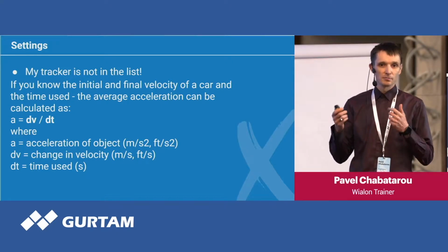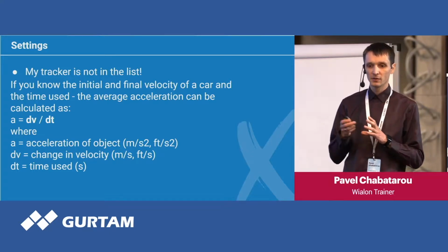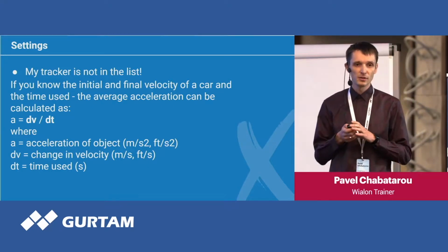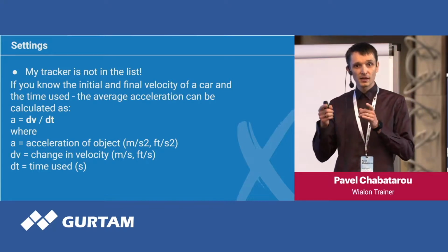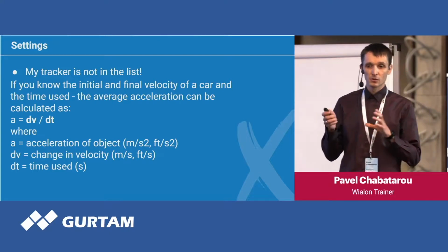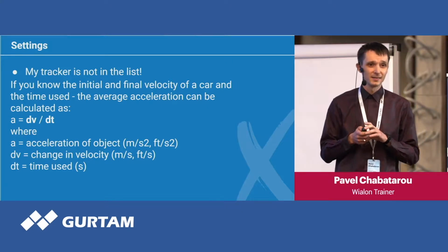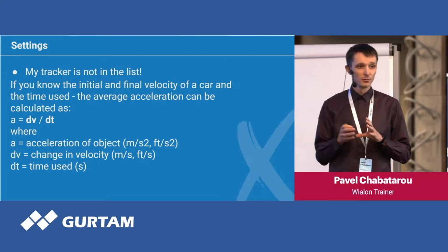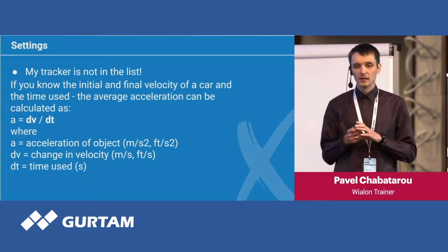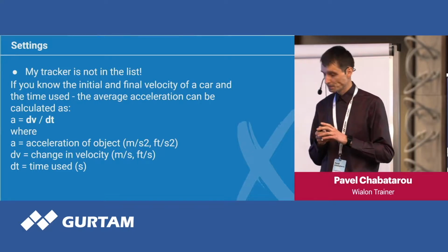Wialon allows to receive and store data and messages with the time difference of 1 second. So each 1 second, we can receive a message and store it in the unit's history. And so every second, we can calculate the acceleration. But just so you're aware, mostly the car accident lasts for less than a second, like 200 milliseconds maybe or so. So it's a very fast event. And again, it is better to use special equipment that is in the supported list at our hardware page.